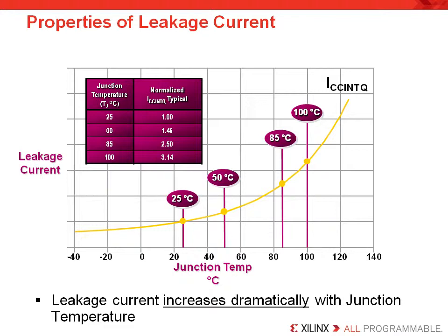Another interesting property about leakage current is that if you increase the environmental temperature, the leakage current goes up exponentially. Now this is a very normal CMOS behavior, but with smaller geometries, the extent to which this curve becomes steeper at higher temperatures gets worse. So it is very important that you manage the temperature of your device by whatever means necessary. This may require the use of fans and/or heat sinks in any FPGA application.